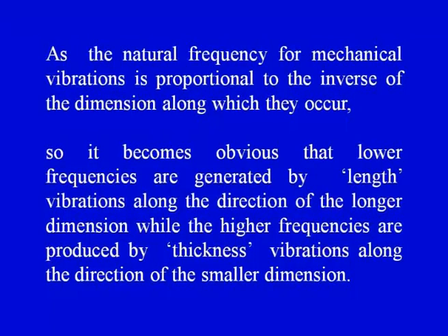As the natural frequency for mechanical vibrations is proportional to the inverse of the dimension along which they occur, it becomes obvious that lower frequencies are generated by length vibration, that is along the longer dimension of the plate, while higher frequencies are produced by thickness vibration, that is along the direction of a smaller dimension.